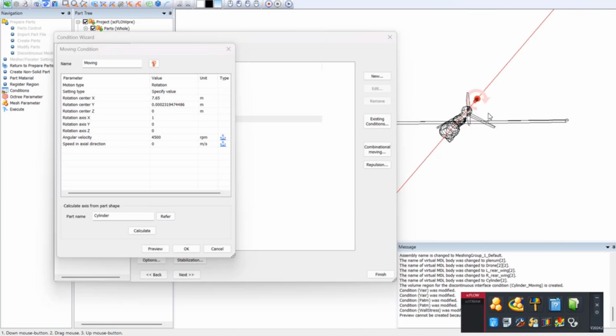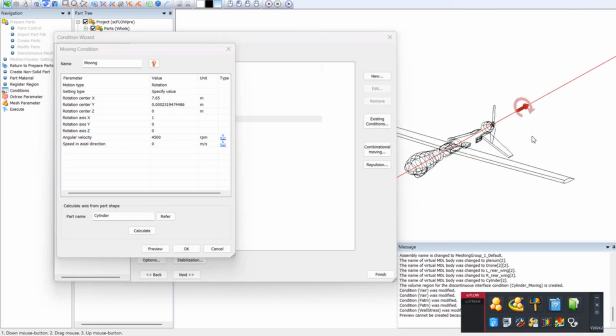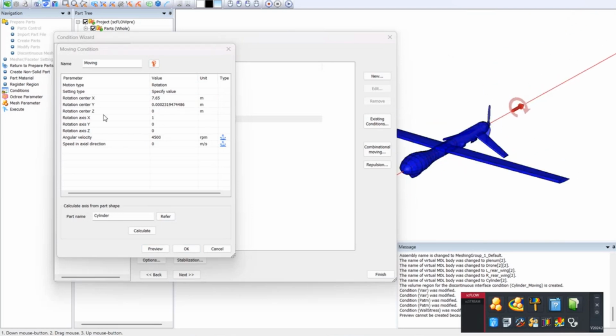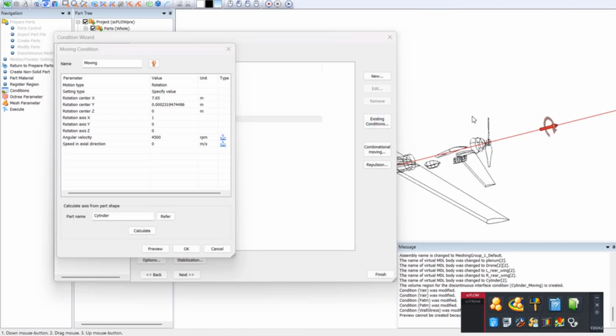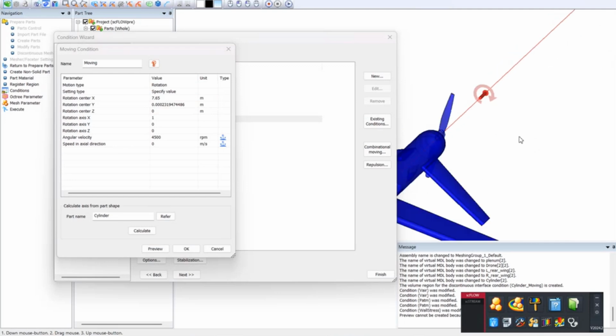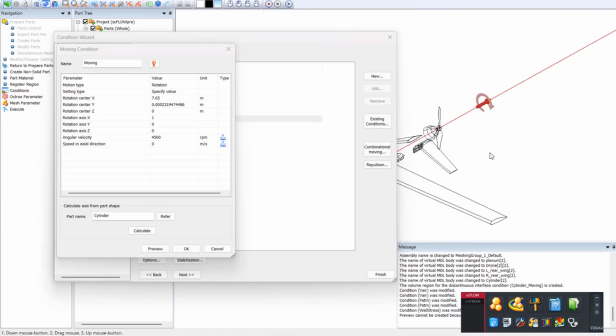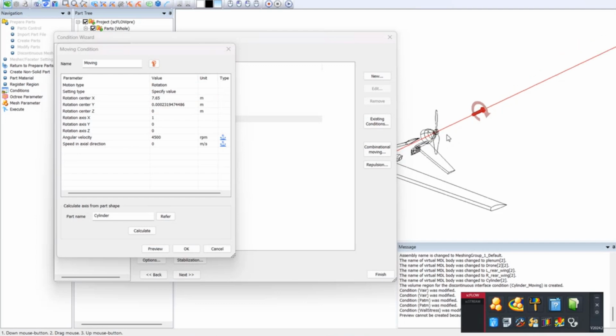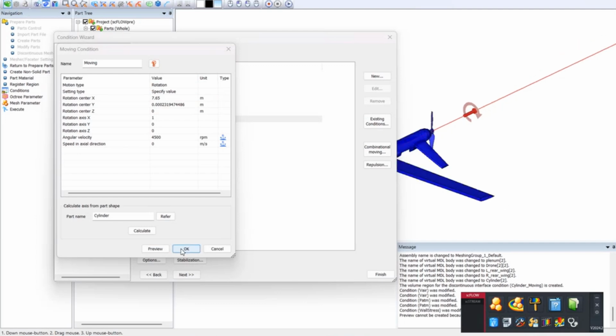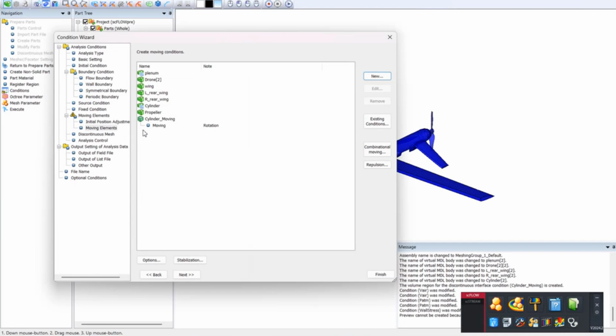If it's not corresponding to what you have in mind for your motion, you can, of course, change the position of the axis and its orientation. But here, in terms of rotation, it's quite simple. Automatically, it will identify what will be the rotation axis. And it will also give you a direction of rotation, because I'm the best for that, to launch a calculation and then to realize that the direction should be the opposite. So here they added it a few years ago, and it's very helpful, believe me. So this is the motion that we set here for the model.